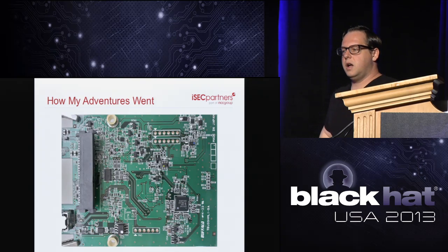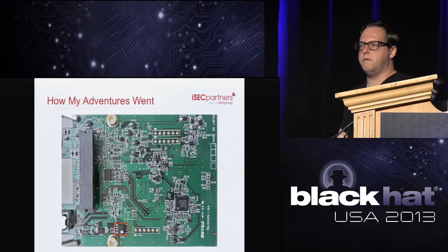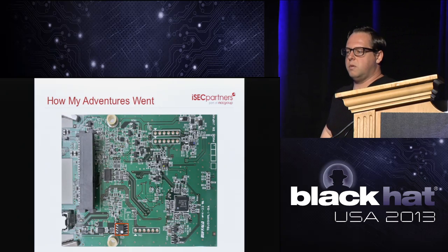Flipping the board over, we identify the fourth chip, the ARM Cortex. Any ROMs on this? We notice there's one over here. Visual inspection, just looking at this side, we don't see any chips around it. Although if we flip the board around, in this image, you'll see a big grouping of resistors right above that, and that's the bottom end of the Thunderbolt controller. So all those resistors are being pulled high or pulled low for power and such. So this may be the ROM for Thunderbolt. We're not quite sure. Visual inspection doesn't show any direct vias to it.